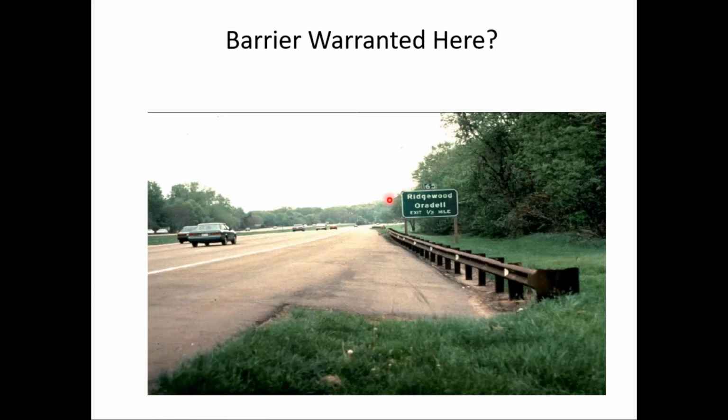it looks like what this barrier section is shielding is this sign, which appears to have timber posts. And I would argue, and maybe many of you were thinking the same thing, I would argue you could make those timber posts break away by drilling holes in them, in which case we could eliminate the need for this barrier, which, as I keep talking about, is and can be a hazard in itself. So I agree with the responses.